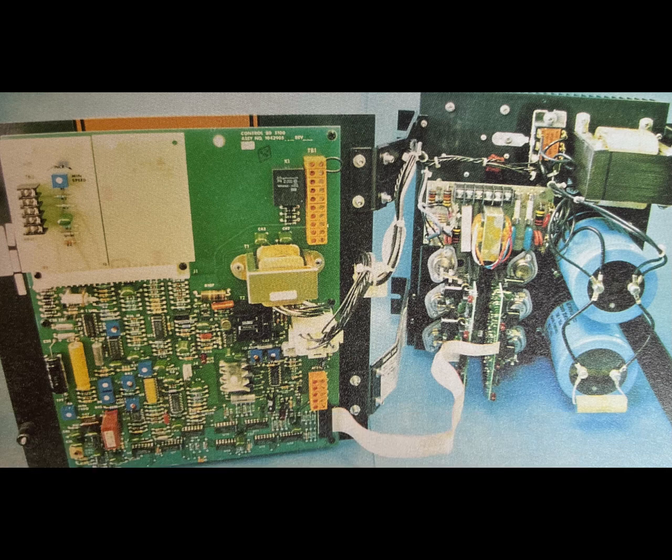When the frequency is lowered, care must be taken not to damage the stator winding. Current flow through the winding is limited to a great extent by inductive reactance. When the frequency is lowered, inductive reactance is also lowered. XL equals 2 pi FL. For this reason, variable frequency motor controllers must have some method of reducing the applied voltage to the stator as frequency is reduced.